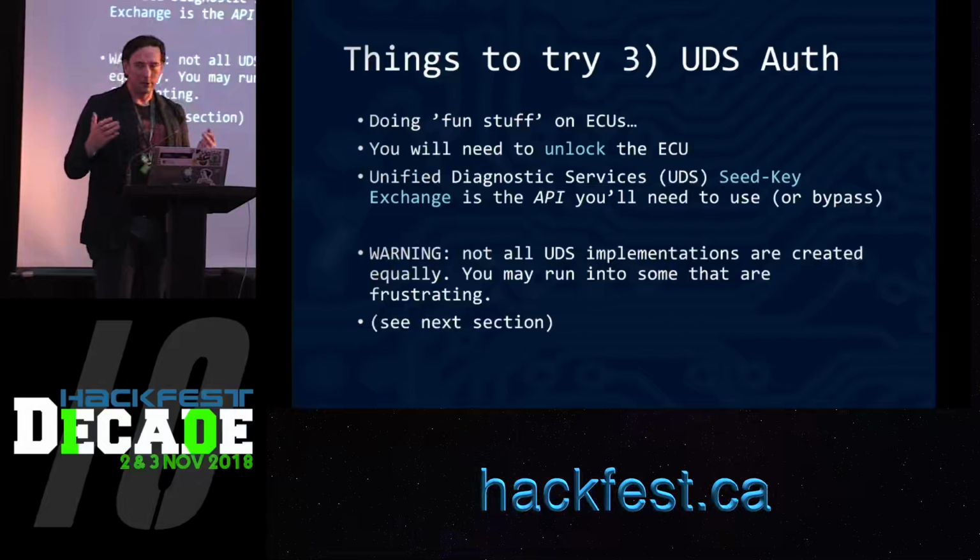The smart thing that Riscure did, and they talked about this year, instead of trying to glitch past the authorization step in seed key exchange, go to one of the really important functions you want, like read memory, for instance, and just glitch at the read memory operation. Because somewhere in that code, the read memory operation is going to check a bit that says, am I authorized? Just glitch the "am I authorized" check in the function you're interested in. Don't glitch UDS itself, right?